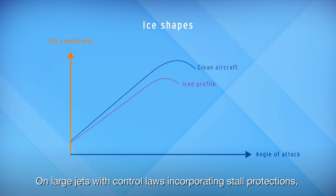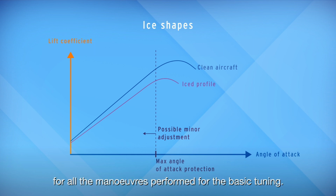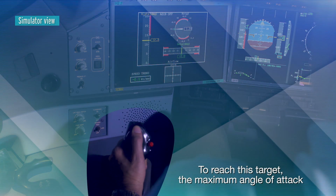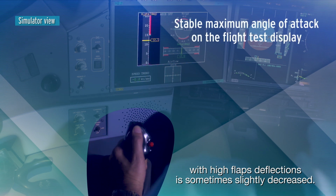On large jets with control laws incorporating stall protections, a check of their efficiency is carried out. Satisfactory results must be obtained for all the maneuvers performed for the basic tuning. To reach this target, the maximum angle of attack with high flaps deflections is sometimes slightly decreased.